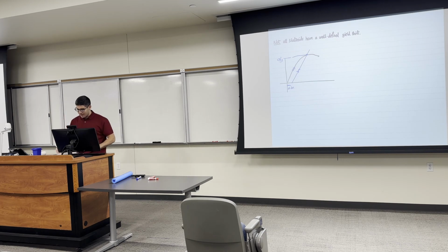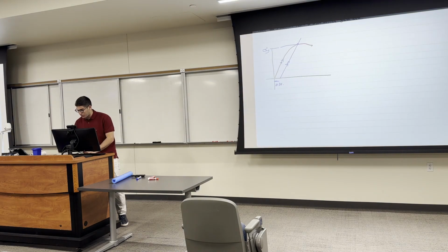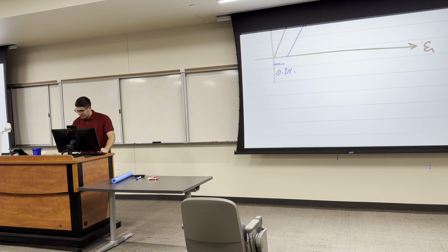So what I said here, if you have a material that doesn't have a well-defined yield point, what should you do? The steps are, it should be a metal, for example, steel or aluminum. You should track the strain, so this point should be 0.002, which is 0.2%.